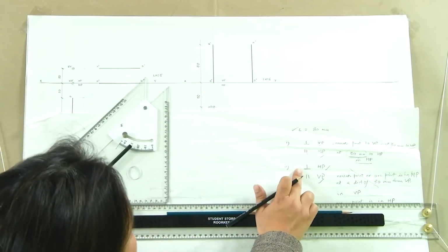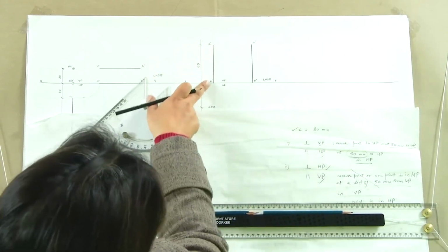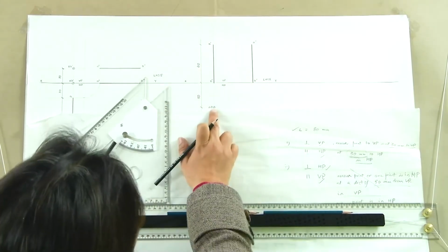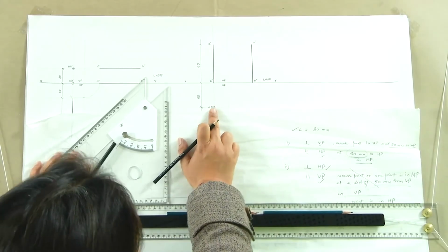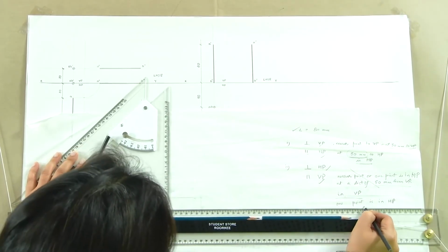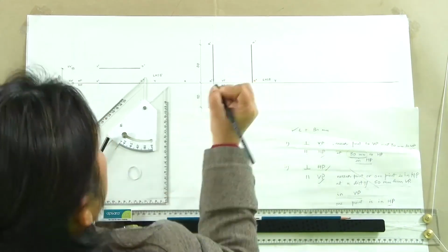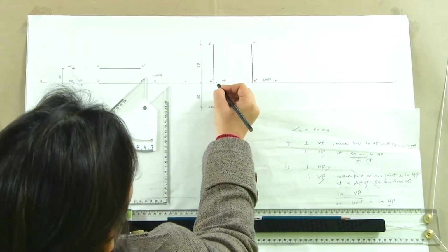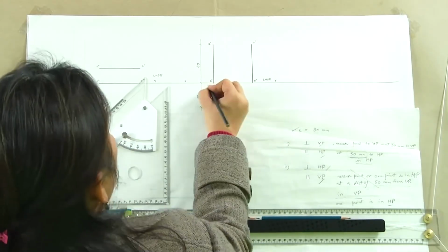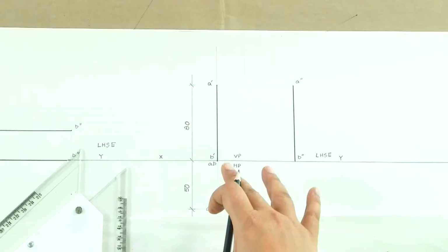So, what we are saying, it is perpendicular to HP and parallel to VP. Parallel to VP, true length seen here, perpendicular to HP, a point, but it is in VP and one point is in HP. So, all that we will do is this point which is here will be B dash and it will also be AB, because this is the same point that we are seeing here.